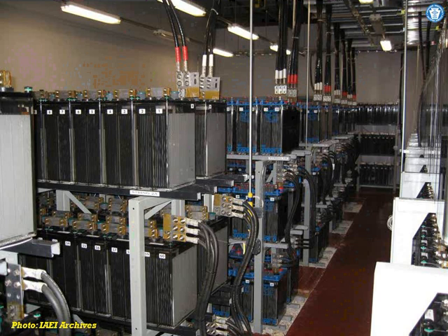That goes into the UPS, and from the UPS it will convert it into AC and dump it across the PDUs. They call them PDUs, power distribution units, that feed the racks you're talking about. So a charging system is continuously charging these batteries. Yes. And if you lose your utility power, it's constantly drawing off this anyway, so you don't even get a bump. Yes, that's the whole idea of a UPS.